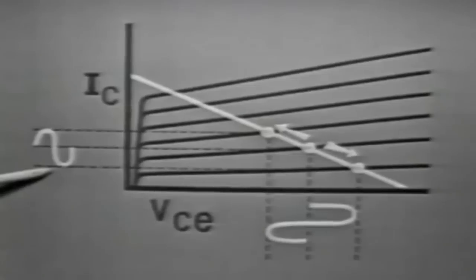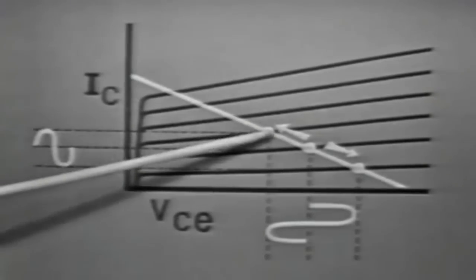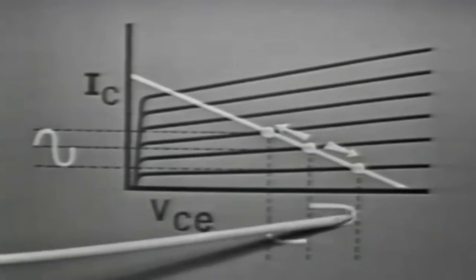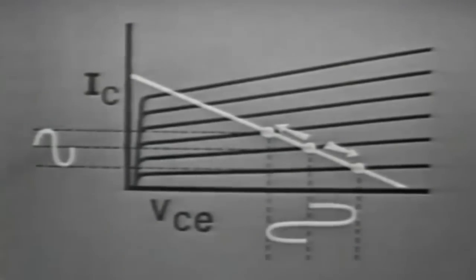This told us the amount of change in the output. We also traced from these 2 intersections on the load line down to the voltage axis on the curve. This indicated the amount of voltage change in the output. Comparing the input voltage to the output voltage, we get an indication of the amount of amplification that the circuit is producing.